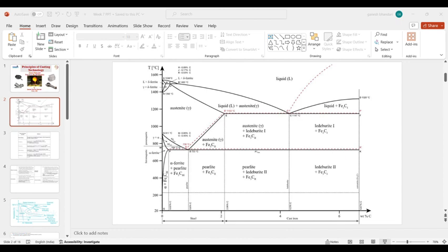Okay, so in the slow cooling process, that whole austenite structure, your 100% austenite structure, is going to convert into your pearlite structure in case of slow cooling. And when we talk about the normalizing process, it is something in the middle. It is in the middle.